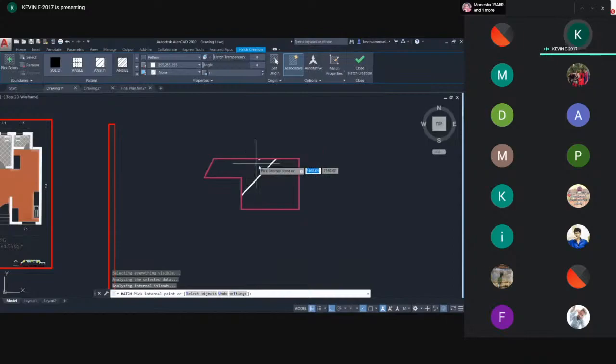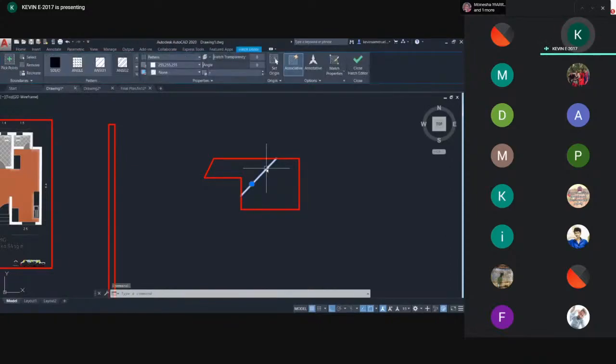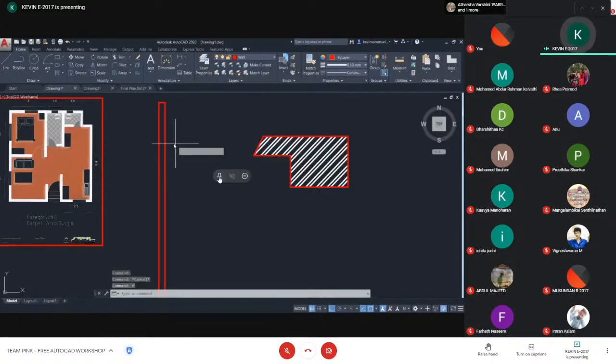You can see here it has hatched the particular object, but the line weight, similarly to what we did for the line type of a particular object, is very huge. So I'm editing the particular hatch, and you can see here there's a number called hatch pattern scale, which is 1. If you reduce it, you will get another line. If you gradually reduce it, around 0.03, you can see this particular object is hatched. Similarly for here also.